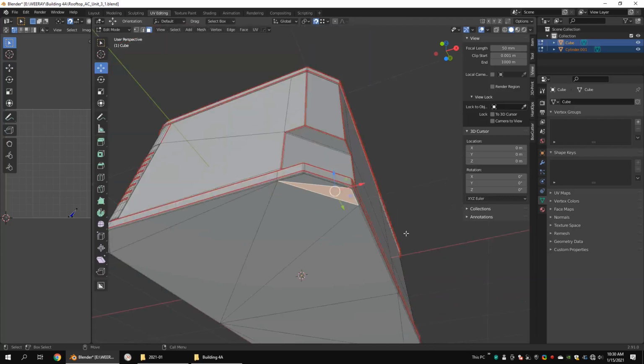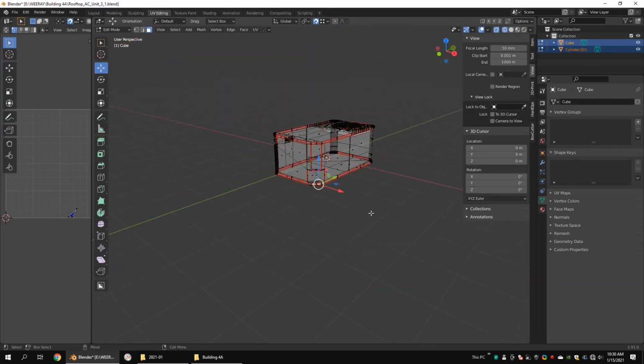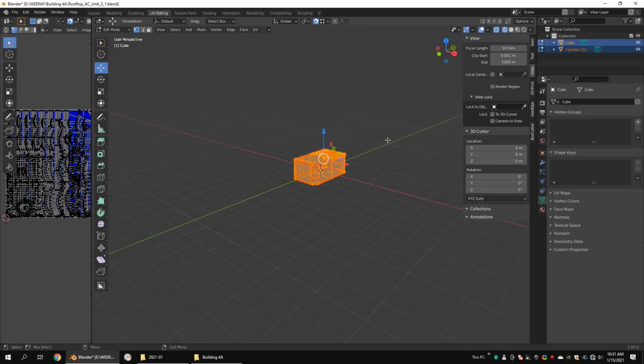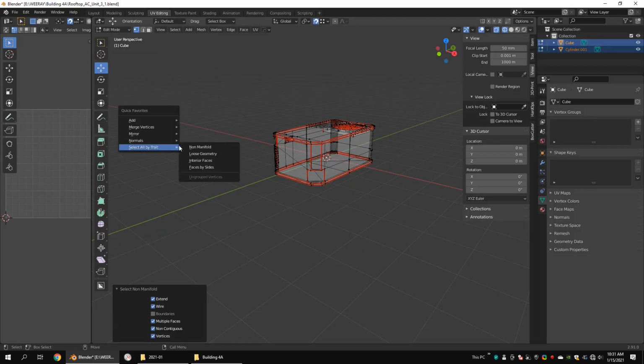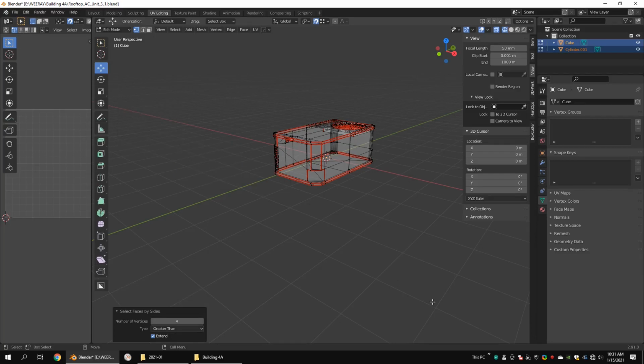When you bake the ambient occlusion map, the shadows of the fan guard grill will appear on the fan. Later we are going to add dirt or dust based on the ambient occlusion map. So when the fan rotates you will see those shadows as well. We don't need the shadows of the fan guard grill to appear on the fan. In Substance Painter I will show you how to bake ambient occlusion map correctly when you are in a situation